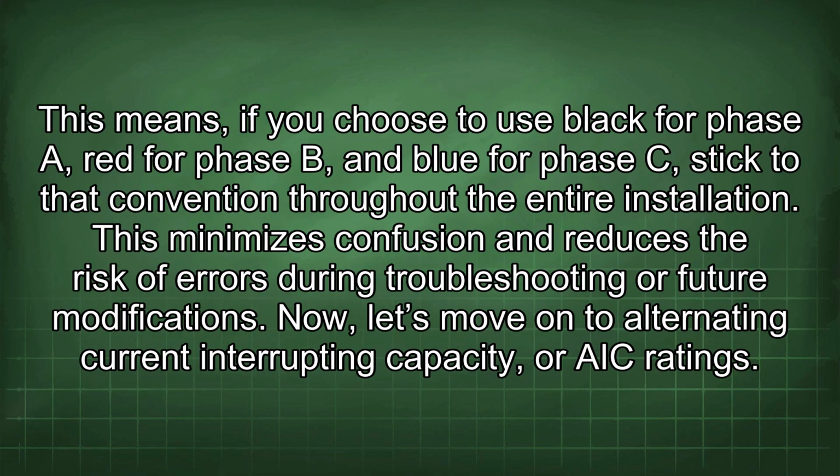This means, if you choose to use black for phase A, red for phase B, and blue for phase C, stick to that convention throughout the entire installation. This minimizes confusion and reduces the risk of errors during troubleshooting or future modifications.